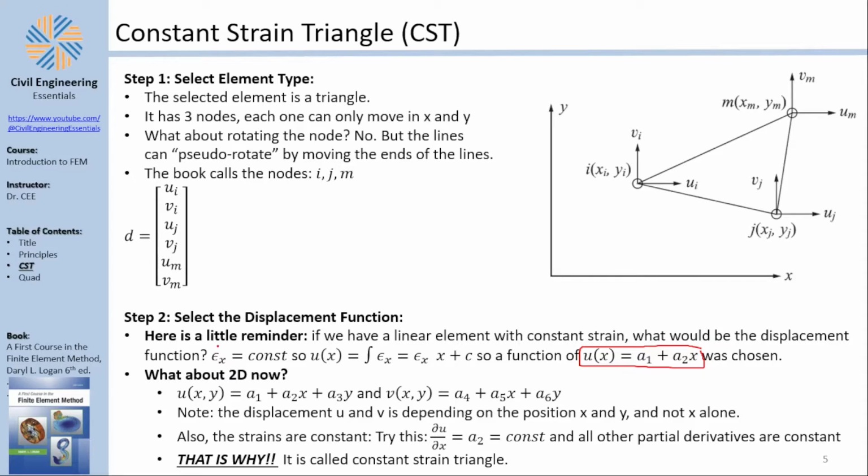You see, in the truss members, an assumption that we can use for the simplified truss element where I have 2 nodes, I explained this as being adequate because I have 2 nodes. But I hid from you a fact that the underlying assumption of a truss element is that the strain is constant on the entire length of the truss. A small wink to MSc and PhD level students, you could add a 3rd node here and make a linearly varying strain in the truss.